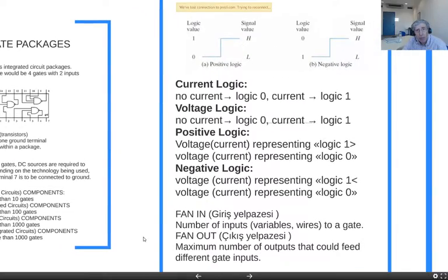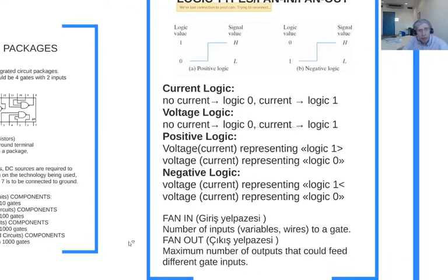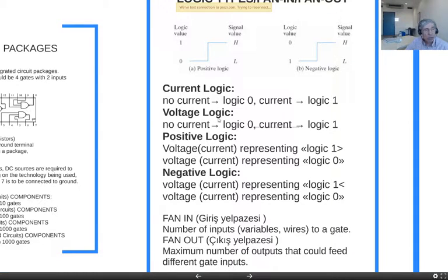Finally, I've got to mention one more thing here. We've got zeros and ones in theory. How are we going to represent these zeros and ones in practice? Electrically, we've got two variables, current and voltage. So we can represent this theoretical 0 and 1 by current and voltage. When the voltage is 0, it is logic 0. If voltage is different from 0, then we can represent 1. If you use voltage, we call it voltage logic. You could do the same 0, 1 representation by using current, so it becomes current logic.